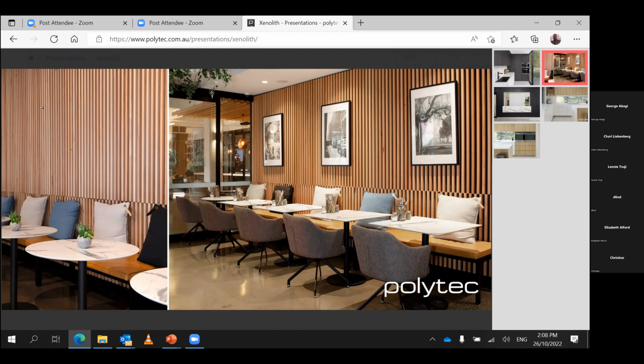And the wall lining has really become very popular because if you're building pods, for example, having stone or tiles normally cracks in the movement. You can have a 5 mil compact straight onto the bathroom pod. We see it being used a lot in hotels. If you want Calcutta marble, for example, on the back of the shower wall, it's quite expensive. By the time you come to build a shower, the cost is gone. So the 5 mil compact laminate just works tremendously.